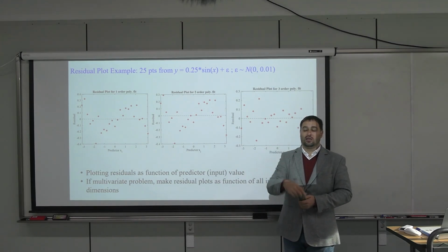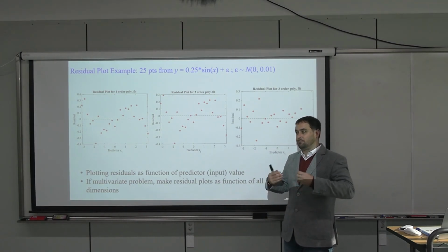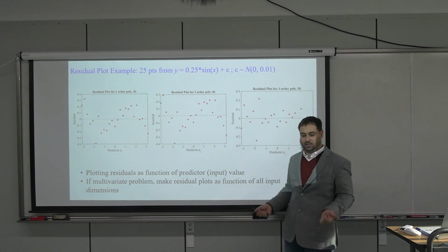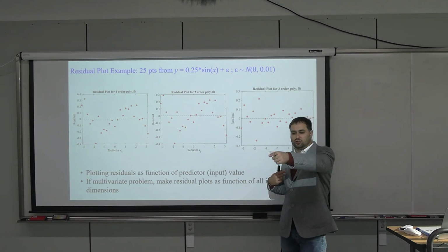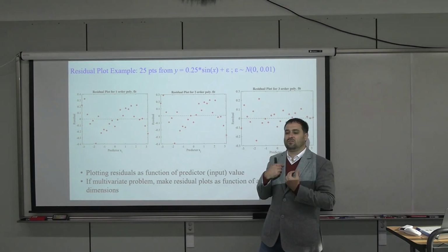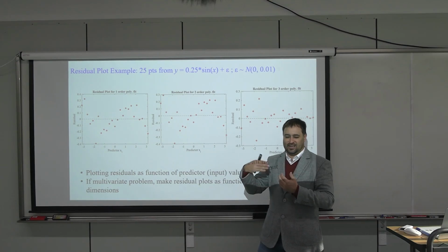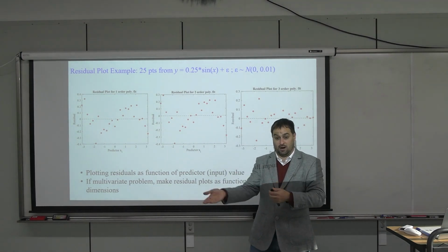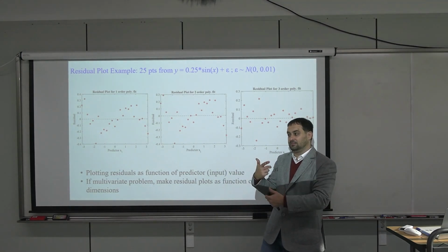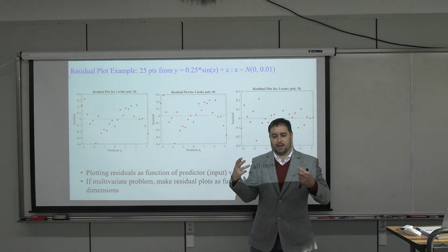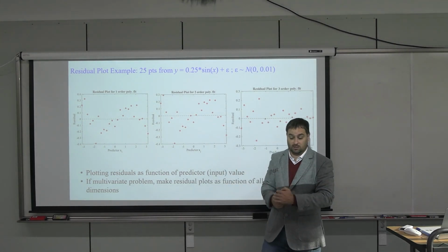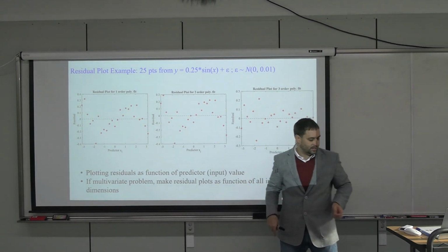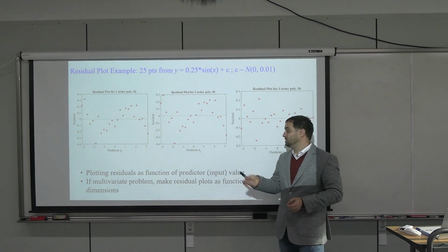Say I did some heat transfer experiments and developed this correlation, and you want to use my correlation in your research. You have to make the subjective opinion: do I think this is a good correlation? I don't know this researcher. I wasn't there when they did the experiment, but at least I can make a subjective determination: do I think they did a good job with the regression model based on the data set they had? And without residual analysis, you can't do that. And so it's mandatory. You need to do the residual analysis.